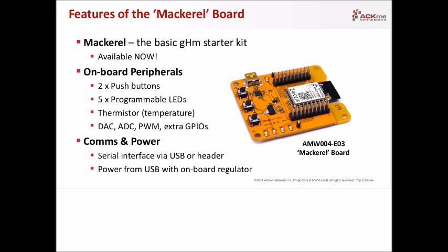It's got some programmable LEDs. It has a thermistor, and it also has, via the GPIOs, the ability to output a digital analog converter output and some ADC inputs, pulse width modulation, and some extra digital GPIOs to control things.